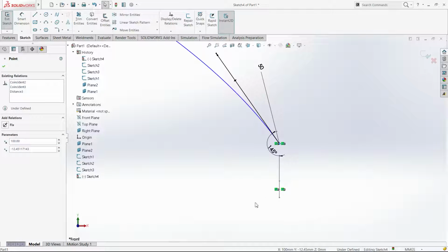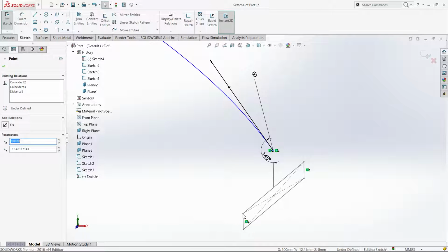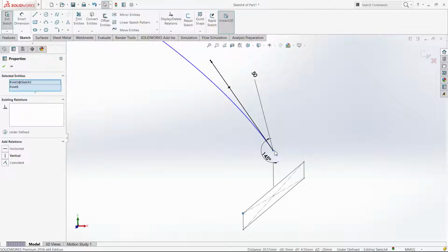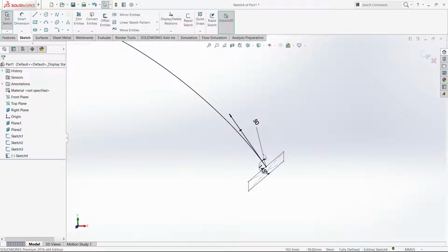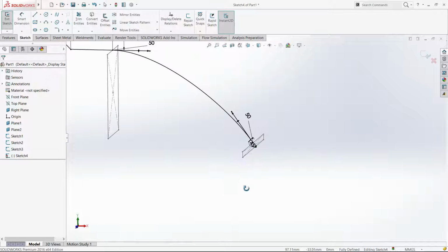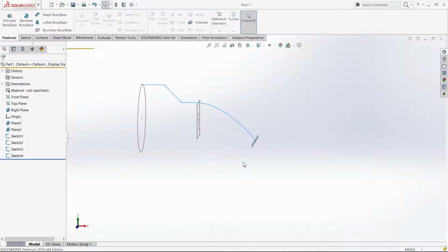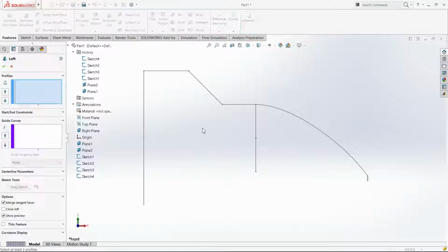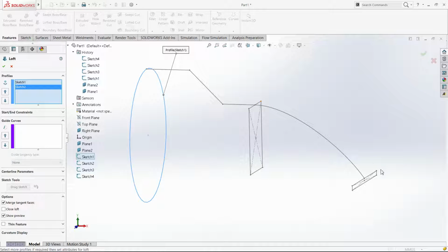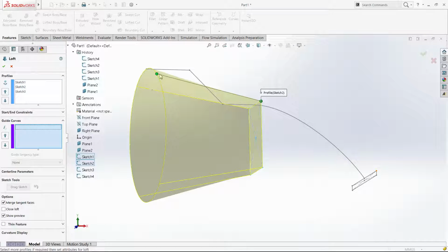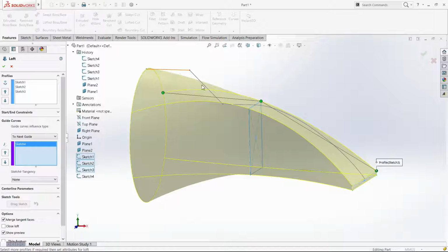So if I go that point and that point, I can make them, well, I cannot do anything really, it seems. Yeah, I can just say coincident, but you see that point and that point are gonna be coincident in the same sketch plane, while in merge, it's gonna be protruding through that line. So that's the difference. So let's see what happens when I do the loft. So you just have to remember where you're clicking, the actual place that you're clicking. And if you go guide curves, you'll probably get your selection manager.